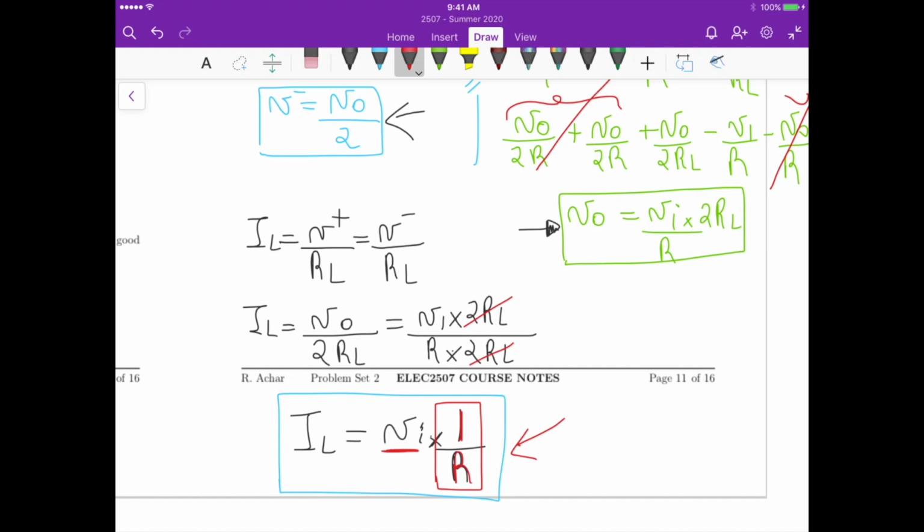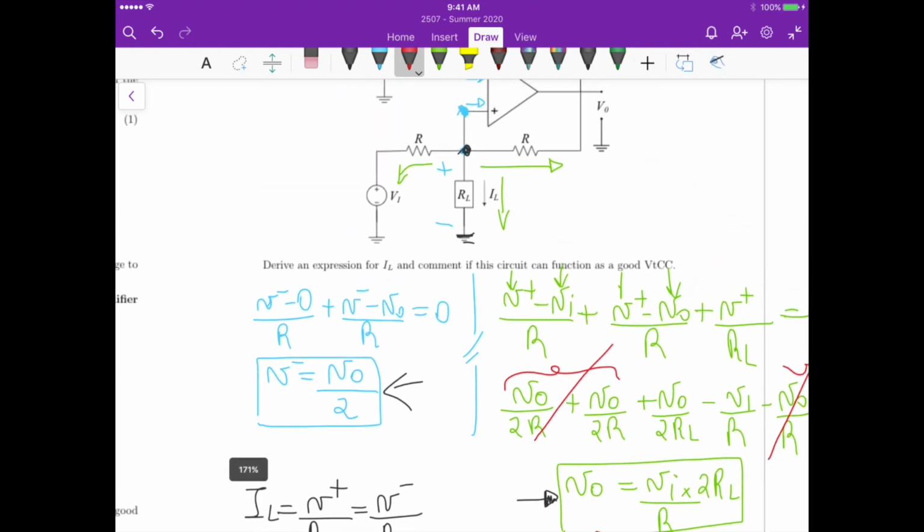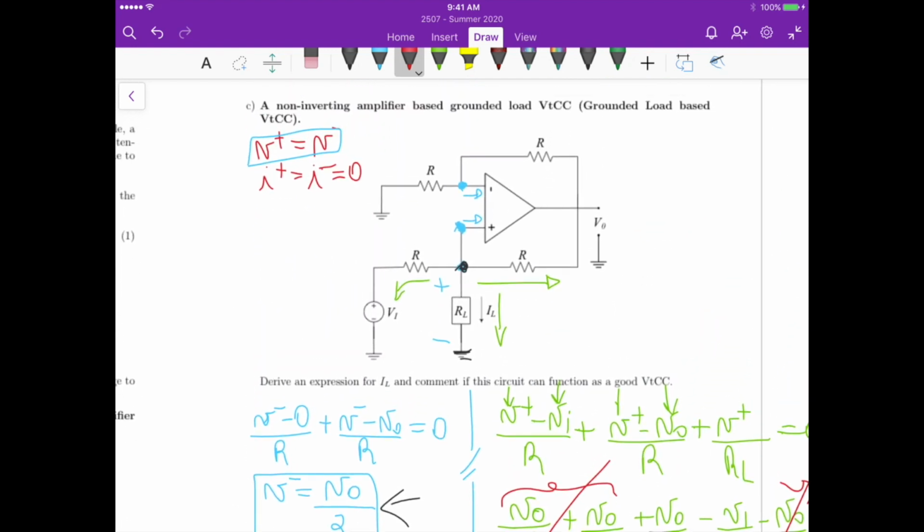And another thing is that if we use a load resistance that is zero, like a short circuit, the voltage here at the output will be clipped by the voltage that we are feeding our op-amp. The internal circuit of the op-amp has some terminals here and here that we use as plus VDD and minus VDD.